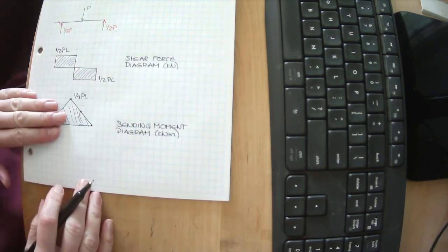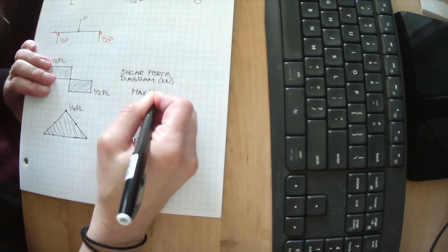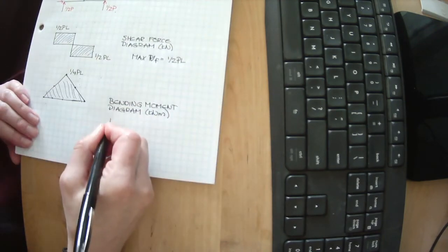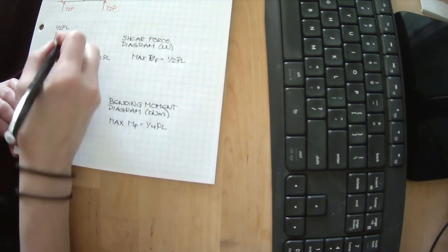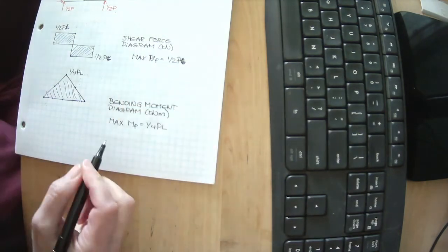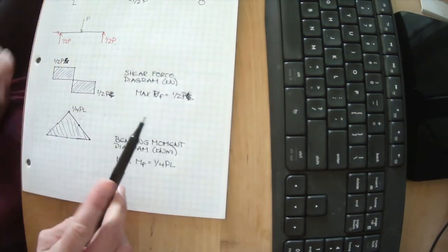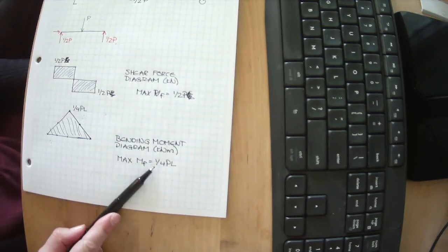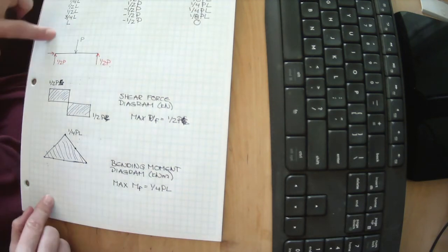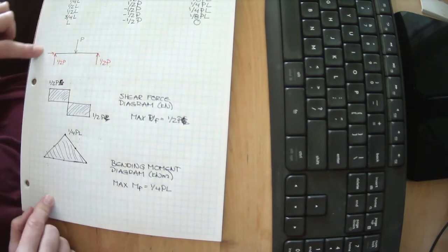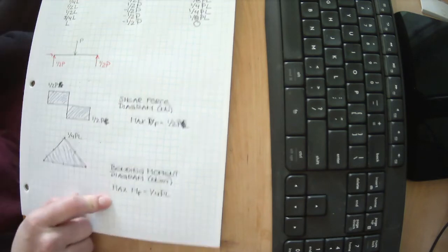So that is our moment diagram, and that's our shear diagram, but we always like to know what the maximum values are. So max V is 1/2 P, and max M is 1/4 PL. Oh, sorry, these aren't L's. Just 1/2 P. Don't mind me. These were all just P. There was no L in those. Scratch that out. So our maximum shear is half of the load, and our maximum moment is 1/4 of the load times the length. We did all of that work to prove that for this free body diagram, we have a maximum shear and a maximum moment that are pretty easy to calculate now. Do we ever have to go back and do another one of these? We have our information right here.